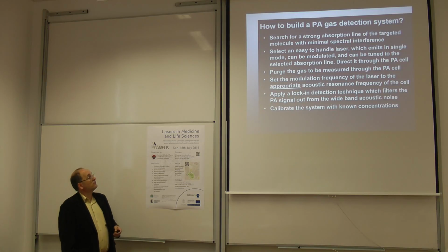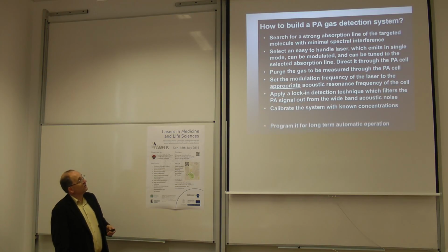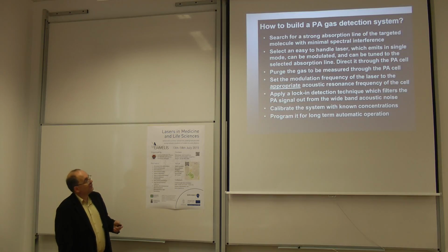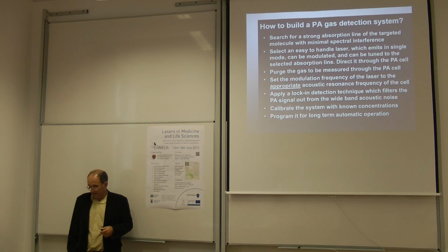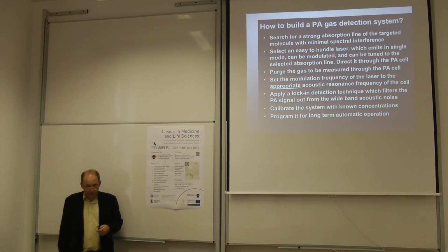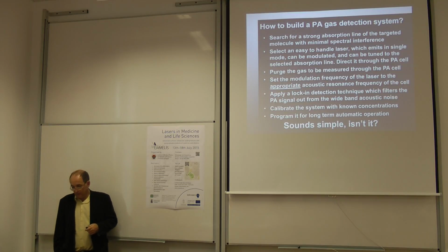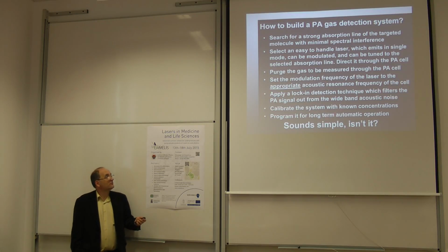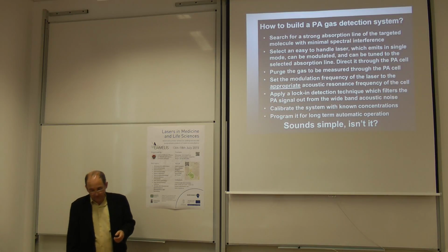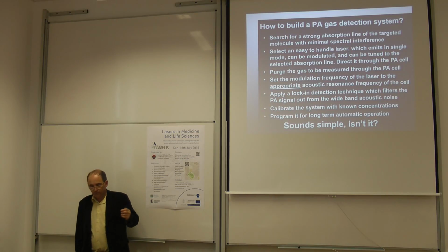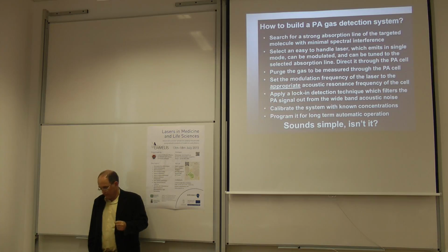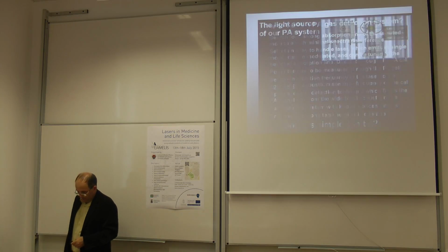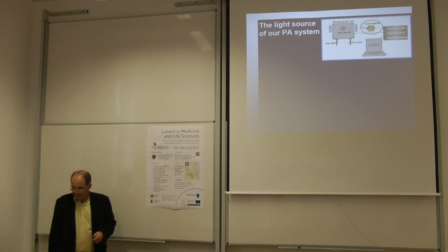And finally you have to calibrate the system with known concentration, and once you have the calibration constant, you can program your photoacoustic system for long-term automatic operation. So actually it sounds quite simple, but there are of course details which have to be taken into account.